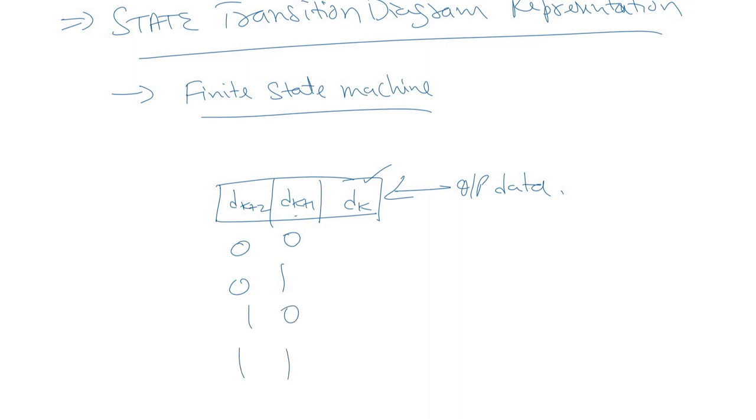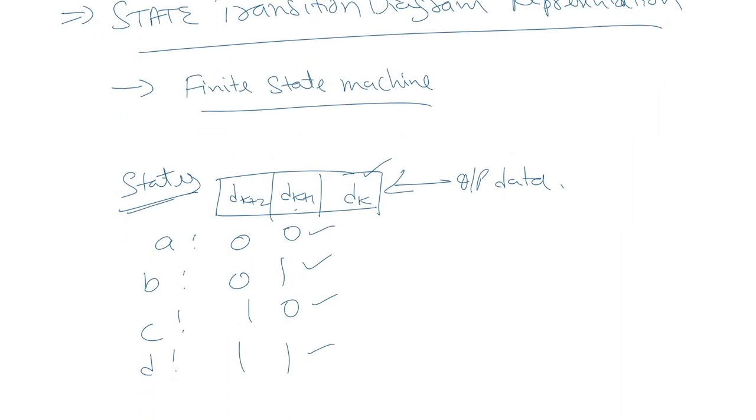Let us name these states A, B, C, and D. These are the states of the shift registers, the 4 possible states depending on the 2 inputs already present, or we can say the possible states of the encoder.